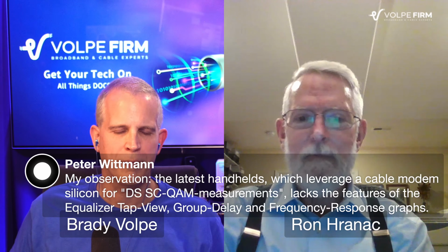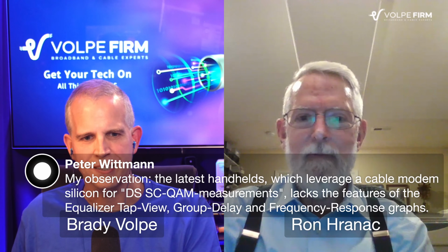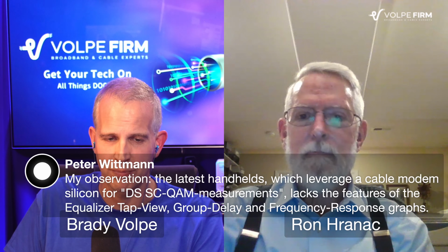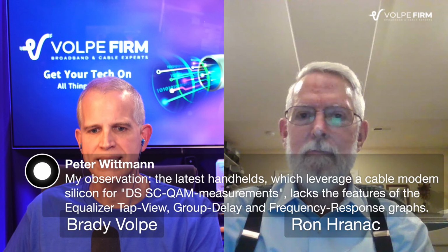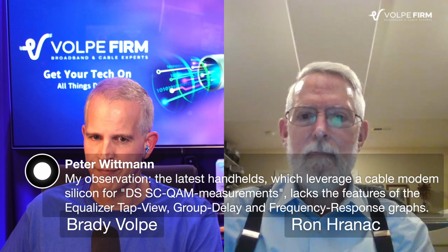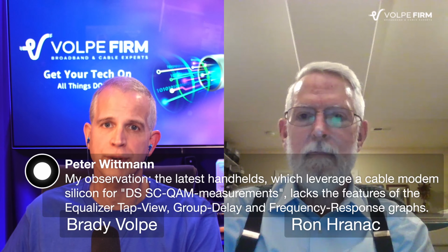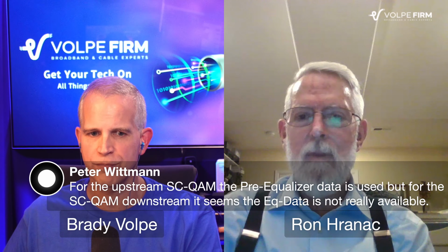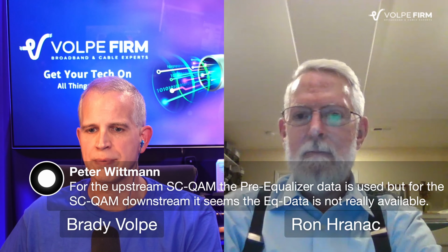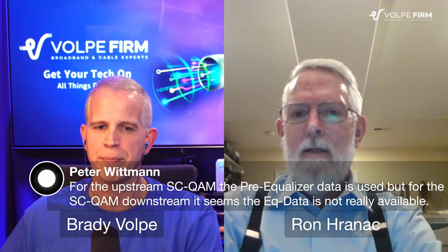We have a comment from Peter Whitman. Peter, welcome back to the show. He says, my observation, the latest handhelds, which leverage cable modem silicon for downstream SC-QAM measurements, lack the features of the equalizer tap view, group delay, and frequency response views. He says for the upstream, SC-QAM and pre-equalizer data is used, but for the SC-QAM downstream, it seems the EQ data is not really available. And maybe that's why you're not seeing some of that functionality in some of the newer meters, Ron.